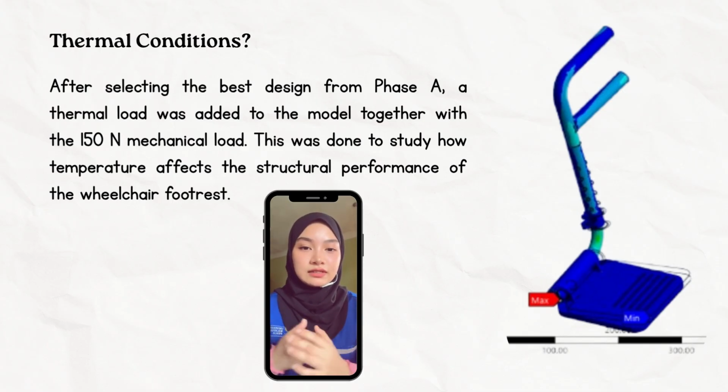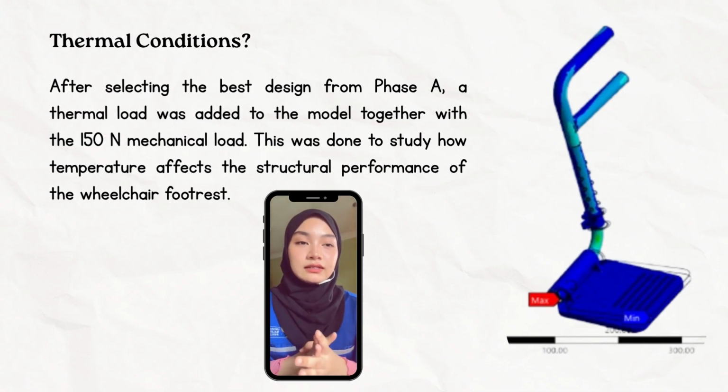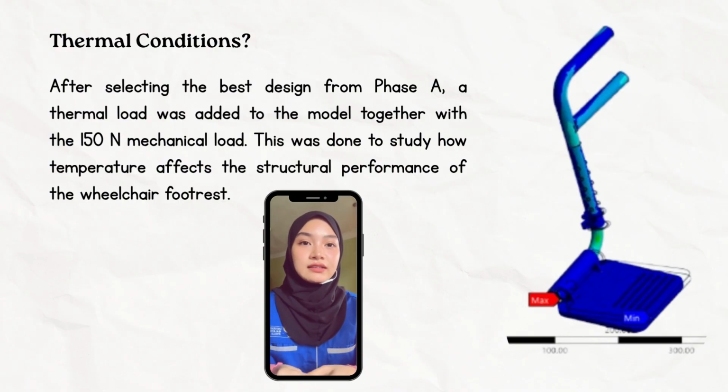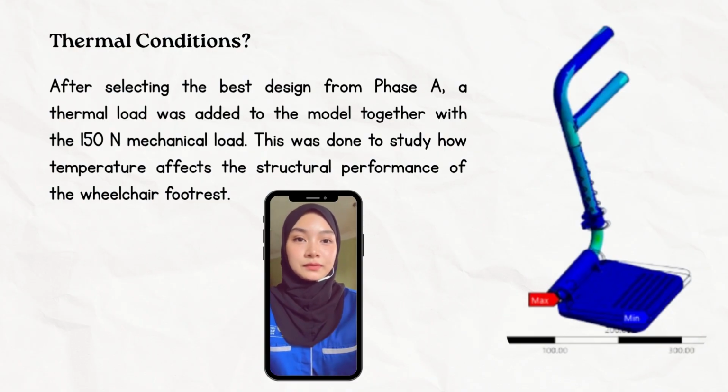After selecting the best design from phase A, thermal analysis was carried out. Besides the mechanical load of 150 Newton, a thermal load was also applied to study how temperature affects the wheelchair footrest. This analysis represents a situation where the footrest is exposed to higher temperature during outdoor use or different environmental conditions. The purpose is to determine whether the temperature change affects the stress, deformation and overall structural safety.